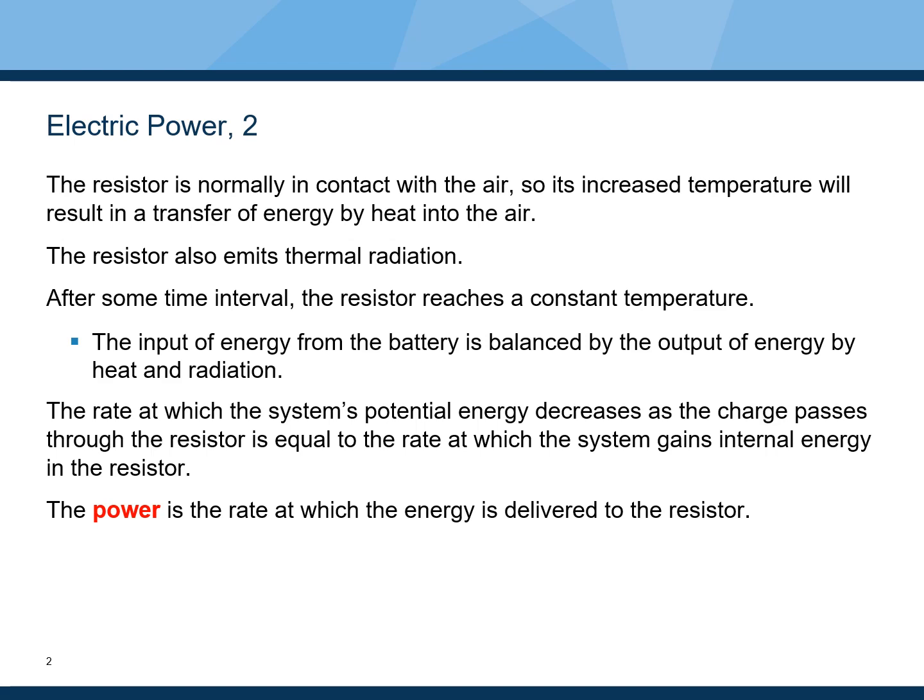The problem with incandescent light bulbs is that they're only about 7% or 8% efficient, which means that if you have a 100-watt light bulb, it's actually giving you about 8 to 10 watts of real luminescent energy, and the rest of the energy is being dissipated as heat, which explains why there's a strong movement towards compact fluorescent light bulbs and eventually towards LED light bulbs, because they have a higher efficiency.